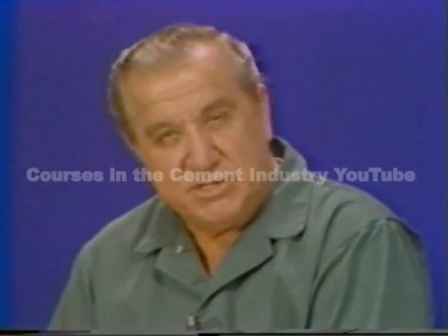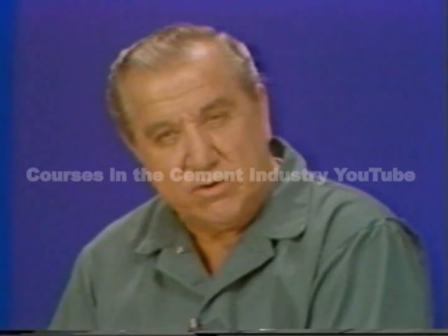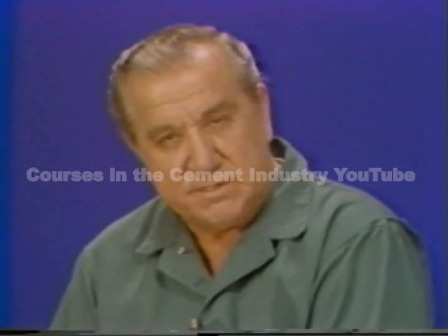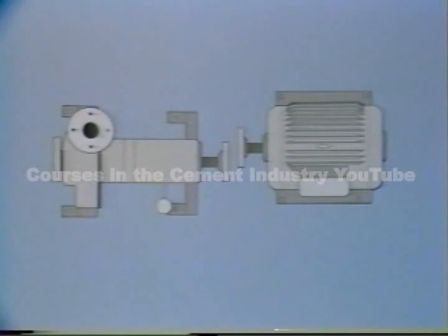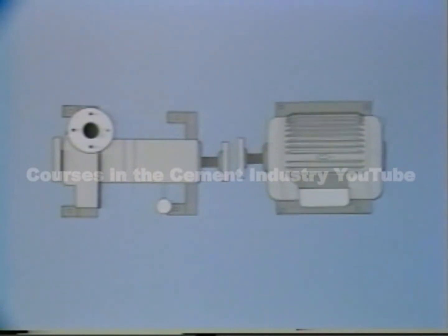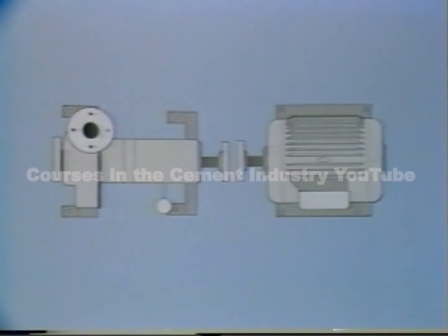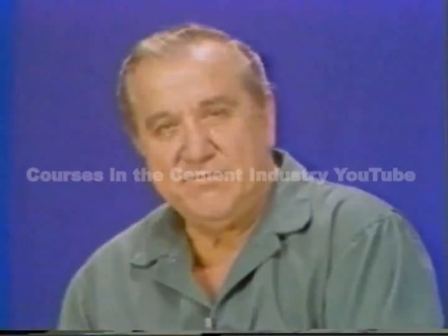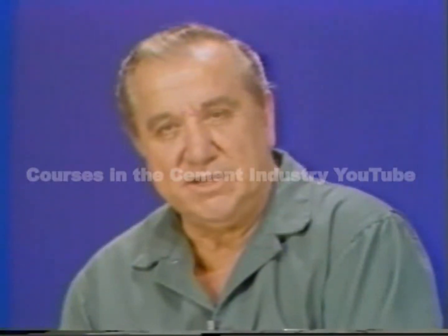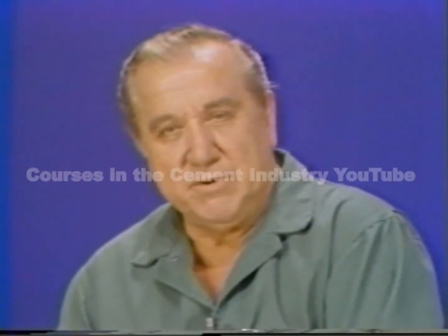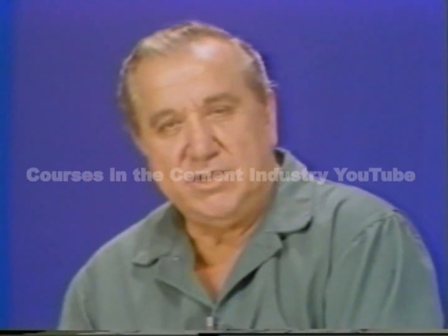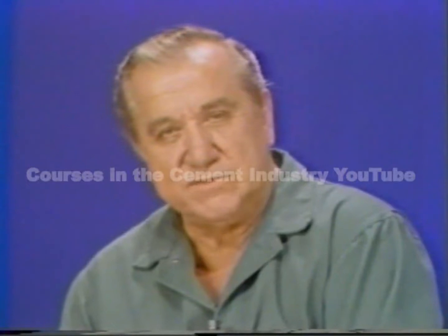To complete the alignment job, similar techniques are used to calculate horizontal, angular, and parallel shifts. Use the same formulas, but this time consider the side-to-side misalignments when viewed from the top. Then you'll know how much to slide the machine and in what direction. Examples of all these calculations are in your text for review purposes. After the shift is made to correct the horizontal offset, a final set of readings should be taken to assure good alignment. Whenever aligning components, always think before you act. Then you'll save time and avoid unnecessary moves.